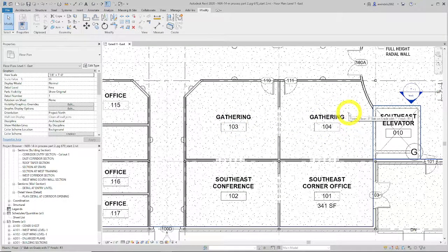So that moves us into room schedules on page 676. Up to this point, a lot of this stuff has been added several times. You have to add it here, maybe on a ceiling plan, maybe also on another plan somewhere else, and then on a schedule like an Excel sheet. So the power of Revit is everything's dynamically linked between schedules and rooms, and you don't have to edit in four places.